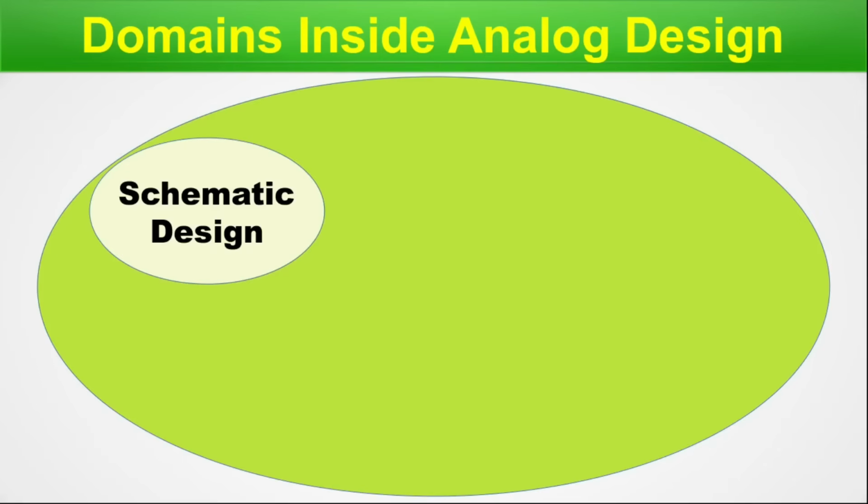In schematic capture, you have a GUI where you can drag and drop various active and passive circuit elements visually and make the entire connection in a point-and-drag method. Thus, you can create a design block, also known as a design unit. You can save this unit in the pre-existing PDK library for reuse at any later time.